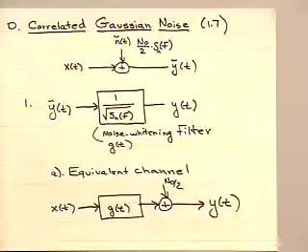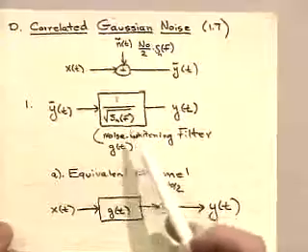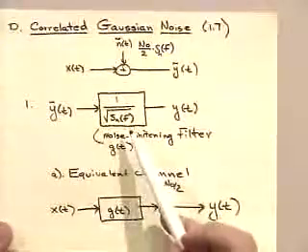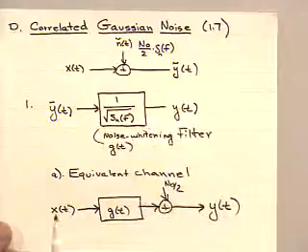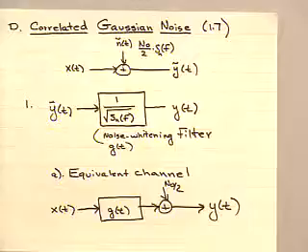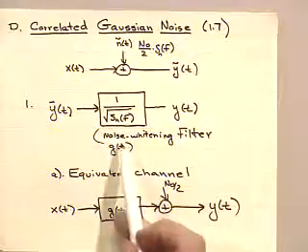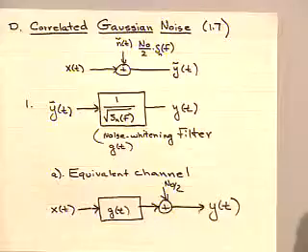Now, its origin is not the same as the channel filtering itself. It has nothing to do with the basis function. It has nothing to do with the channel impulse response. It's an artificial part of the channel that I have, in fact, added myself because I have whitened the noise somewhere in my receiving structure. But if I call the output of that y of t, and this transformation is one to one, by the reversibility theorem in chapter 1, I haven't lost anything.